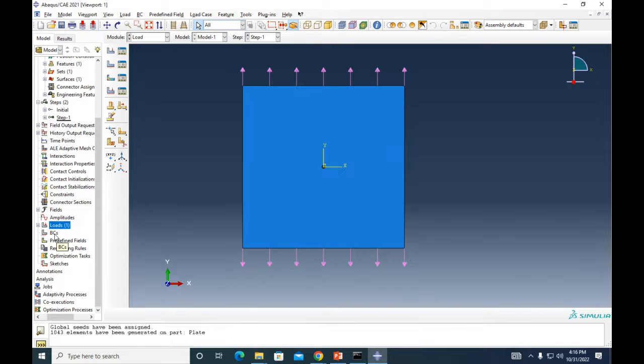So everything that is happening in the y direction, we have a load applied in the y direction. But what have we said to Abaqus about the x direction? Nothing, right? So we have to at least fix 1 degree of freedom in a single node. Otherwise, Abaqus is not gonna give us the solution.